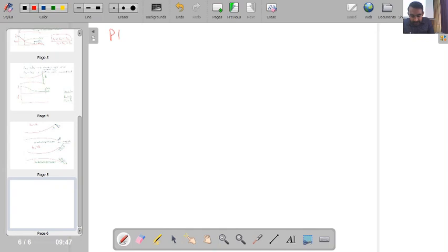So this is my numerical problem 1. Here it is given that the exit to throat area ratio is 2 for a nozzle, the initial pressure is given as 1 atmospheric and the exit pressure is given as 0.95 atmospheric, and you are given a task to calculate the Mach number at the throat and the Mach number at the exit of the nozzle.